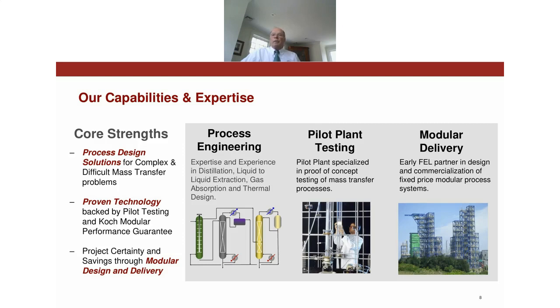And typically what we'll do in this pilot plant is after we develop conceptual process design, if we don't have adequate vapor-liquid equilibrium data, liquid-liquid equilibrium data, we can measure that in the pilot plant, and we can set up a process on a small scale, and using real feed from the client, like 55-gallon drum quantities of customer feeds, we can set up the process and run it to de-risk it.